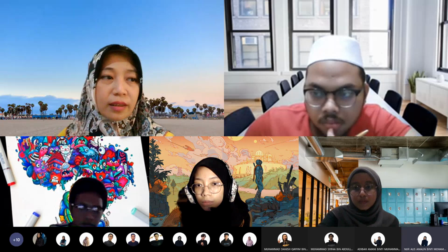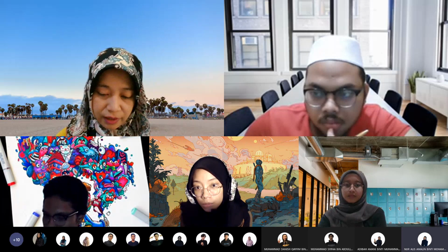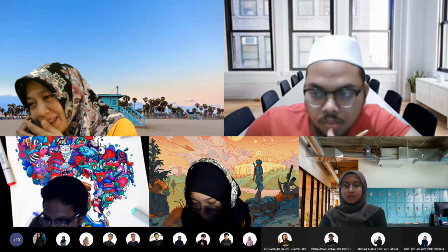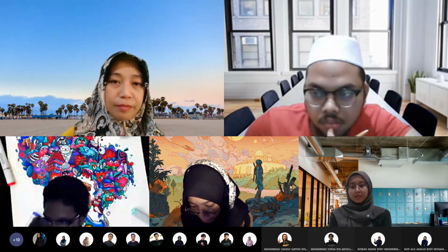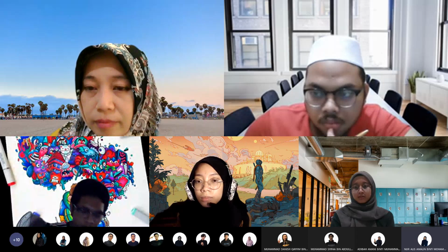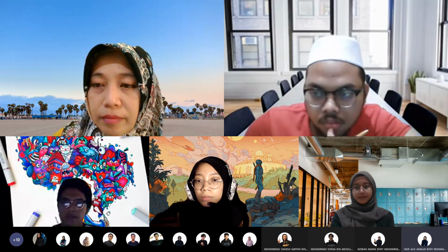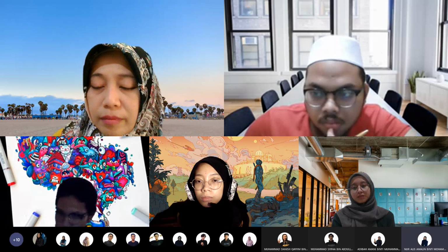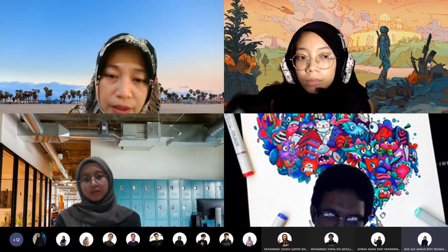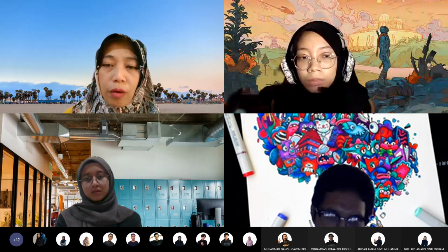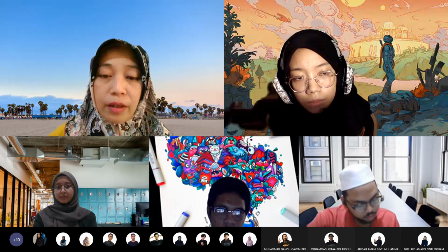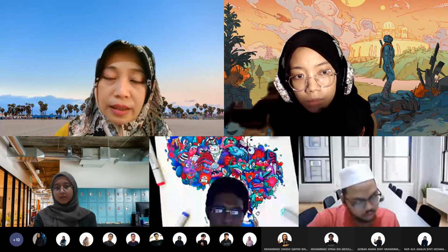Madam, can you explain about the sprinkler area when the distance is 60 for office? Because earlier madam explained the distance to the fire door was 45. What if it is 60? It is like this: if, for example, from one door to another door, fire staircase, it is exceeding 45 meters, the distance has reached 60 meters and above, so that area is considered as a sprinkler system.